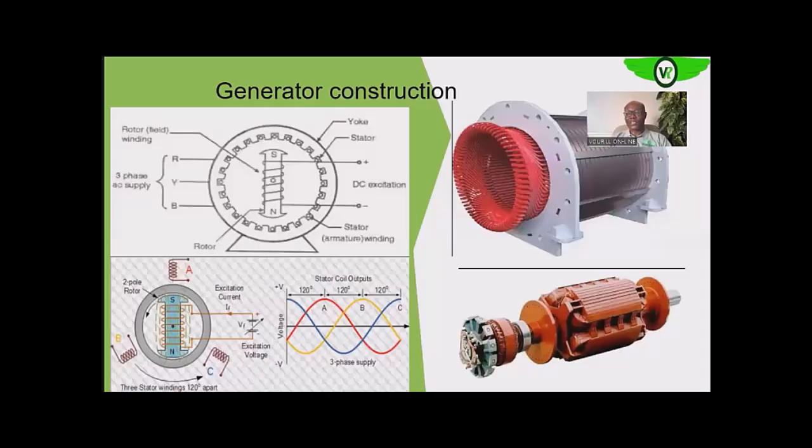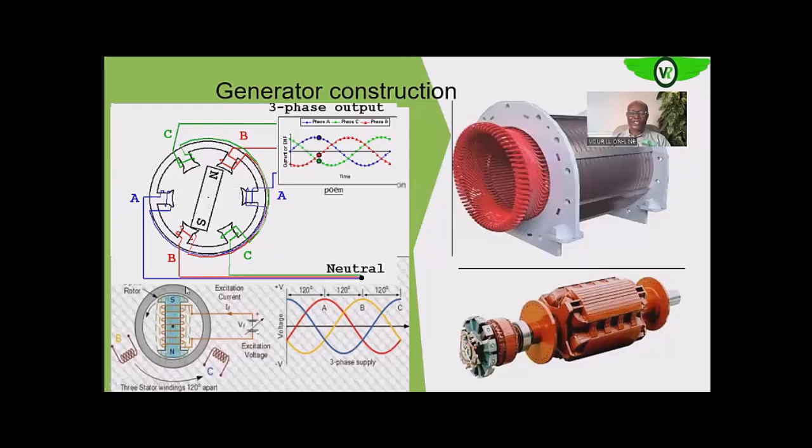Second most important component, which are the switch gears. So on your screen now, this is the rotor. This one is carrying the field windings. This is the exciter armature, which produces this EMF that is sent to the field winding. As the field is rotating within this, you see that since the field is cutting across all of these conductors that make up the A, B, and C phases, voltages are induced into those conductors.